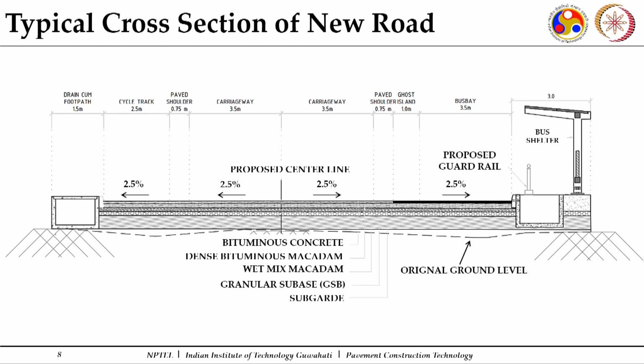You can again see there is a composition. This is a detailed cross section which shows what is there. Here you can see this is the original ground level, and then you have this as your subgrade. So, I'll come to know the subgrade bottom, and the subgrade bottom has to be constructed as per the cross slope. For each layer I will work it out, then I will work out the subgrade top, and I will ensure it during construction also. Then for the granular subbase course, camber has to be maintained, because where you are constructing the drainage layers, the water should flow through your drainage layers.